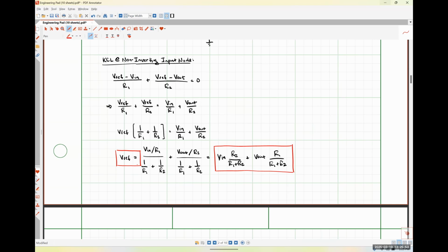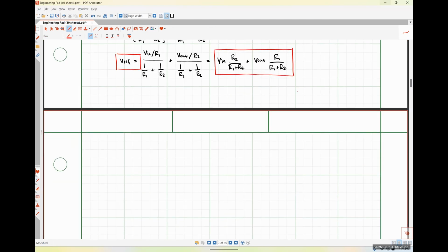So what we're really interested in figuring out here is what value of input voltage makes our output change or transition between those two possible outputs, okay? So we're going to call those voltages the upper trigger limit, which is, let me make a note here. So VUTL is our upper trigger limit voltage.